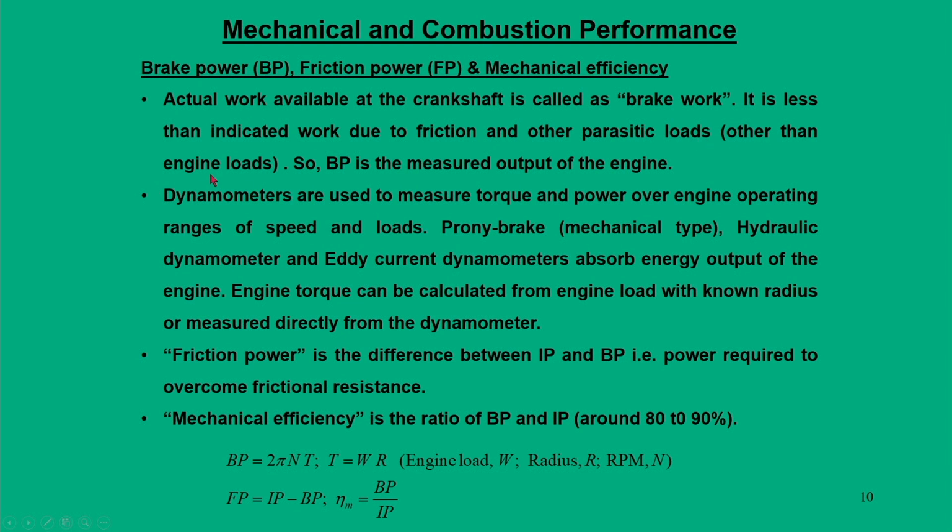For example, in a car we have AC, we have lights, we have other auxiliaries that take power from the engine. Even we have the fuel pump. So, all these instruments take power from the shaft of the engine. These are treated as a parasitic load, which is nothing but the other than engine load. Other than engine load in our term means other than the shaft power. So, this brake power is nothing but the measured output of an engine.